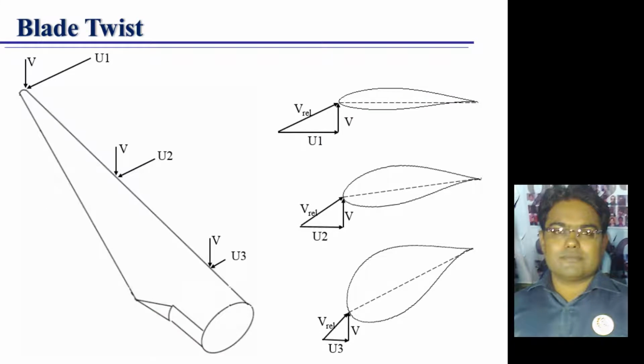So this is the pictorial presentation of a wind turbine blade. We usually provide a slight twist. If we cut it at different locations, like locations 3, 2 and 1, it will have different foil shapes, right? If we focus on the tip of the blade, it is almost a cambered, slightly thicker portion. If we come to the middle, it is a thicker portion. Near the root, the hub point, it will be a much thicker foil section.